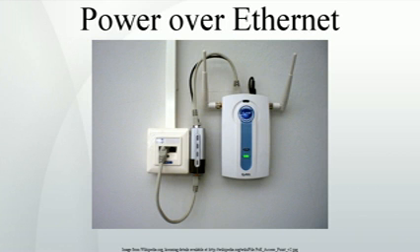The original IEEE 802.3af-2003 PoE standard provides up to 15.4 W of DC power, minimum 44 VDC and 350 mA, to each device. Only 12.95 W is assured to be available at the powered device as some power is dissipated in the cable.